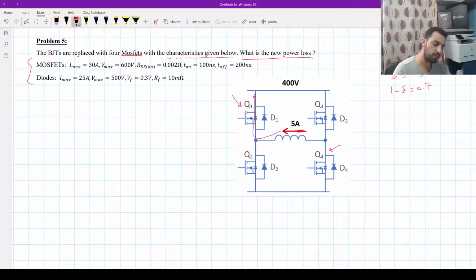now. We will assume that while the current goes through that transistor, it will generate some voltage here. We will assume that voltage is I times R ds on. That voltage is less than the voltage needed to turn on this diode, because if you want to turn on that diode, you just apply across its terminals a voltage more than the forward voltage, which is here 0.3.